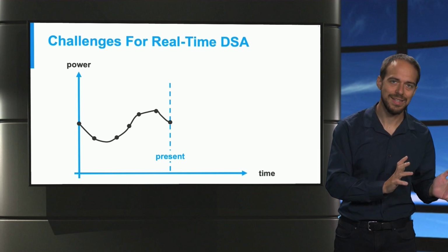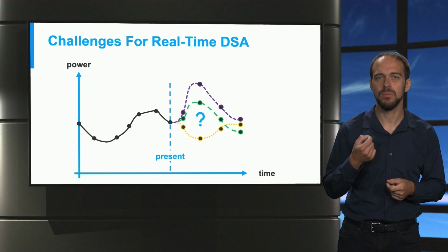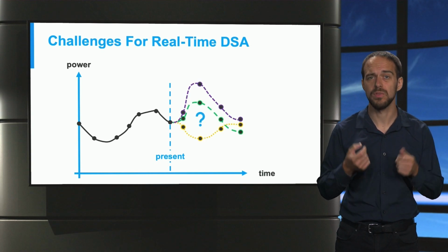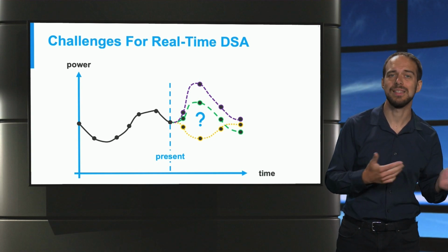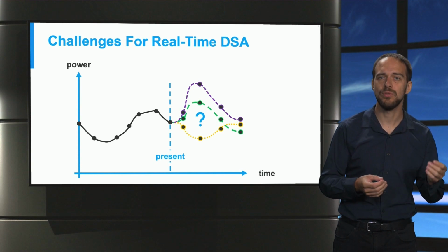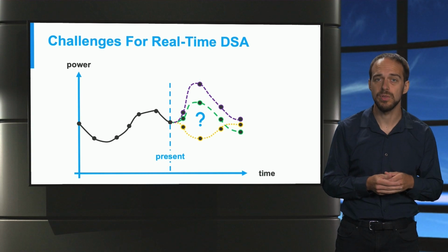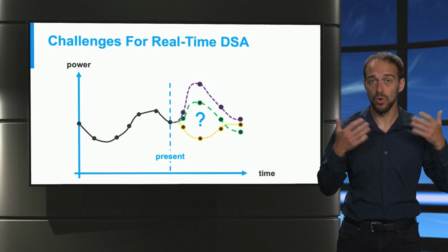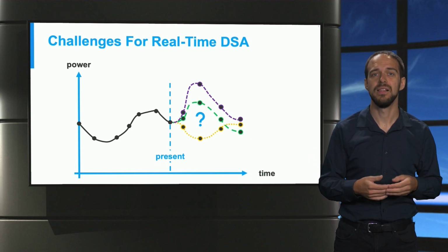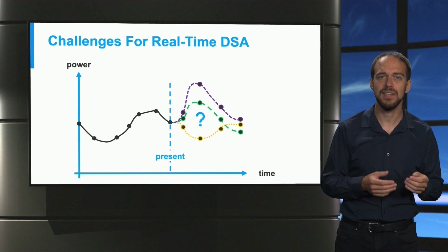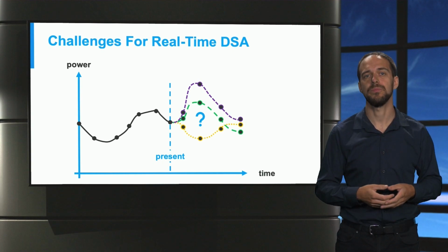The first challenge is that the future is highly uncertain, meaning that many possible trajectories and operating conditions of the individual power outputs are forecasted. For instance, the power of a wind park is highly uncertain. All these different operating conditions must be assessed. This means that the possible trajectories must be considered, all of them. All operating conditions should be evaluated and assessed. This has large computational costs as each condition requires a time domain simulation, which is computationally expensive.